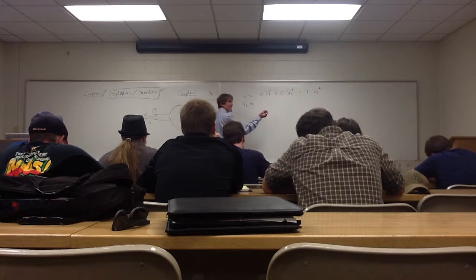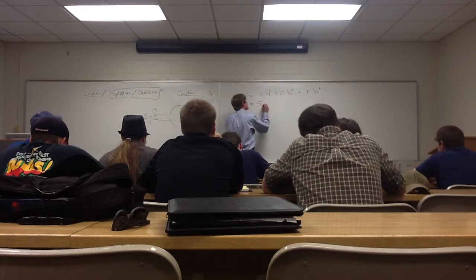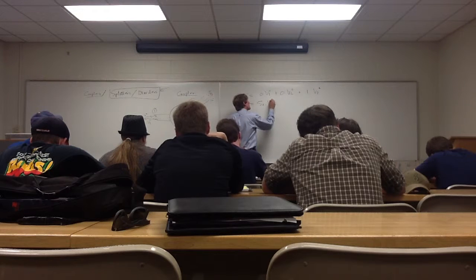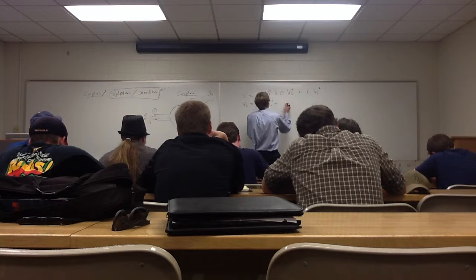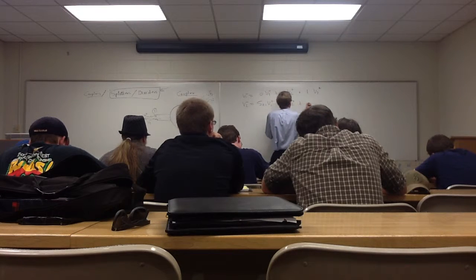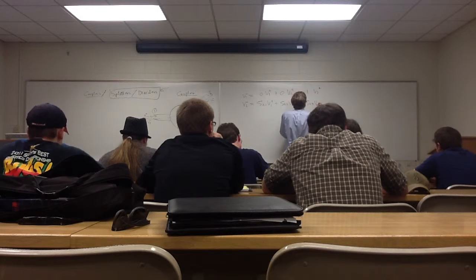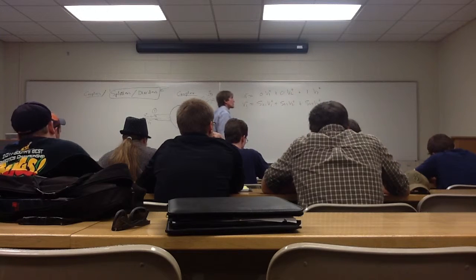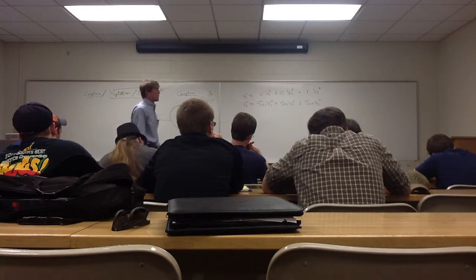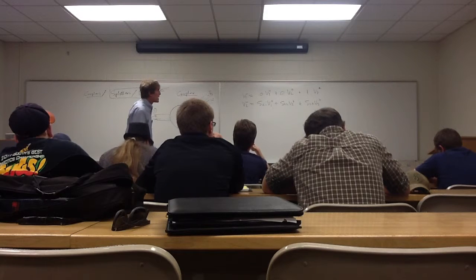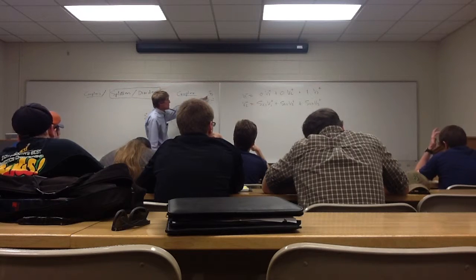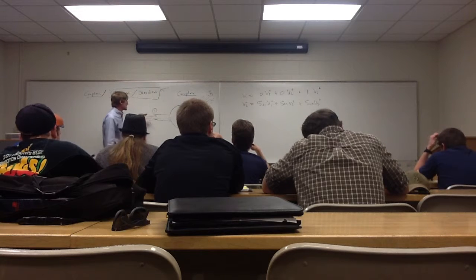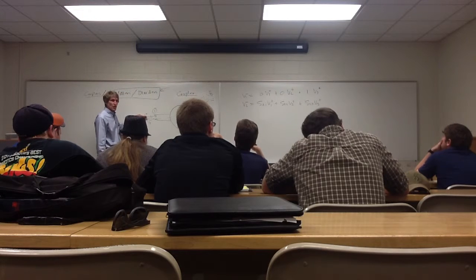V2 minus. When I take a look at this, this is going to be S21 times V1 plus, plus S22 times V2 plus, plus S23 times V3 plus. Everybody with me on this? Now when I look at this, for V2 minus, I only want a signal from V1 to get out on that port.